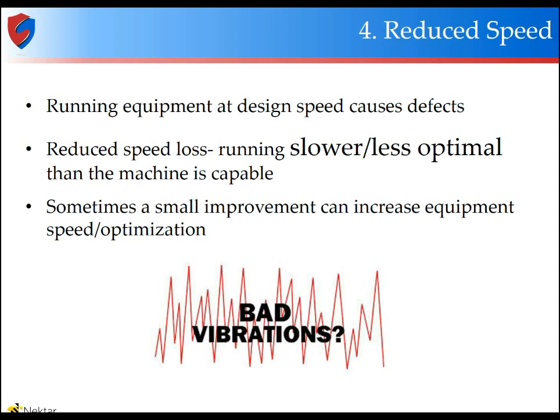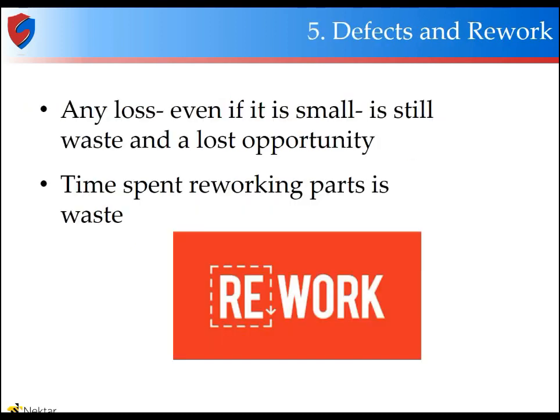And we find that if we run the equipment slower, that vibration goes away and it becomes more robust and reliable. The way to fix this is to get the equipment back to its like-new state, replacing those bearings, bushings, good lubrication, and that vibration goes away. So again, we need to capture this as part of that reliability.